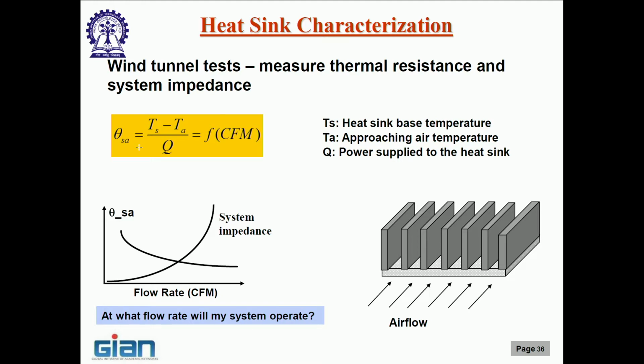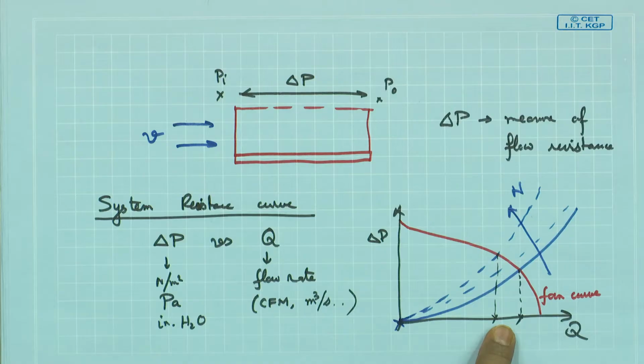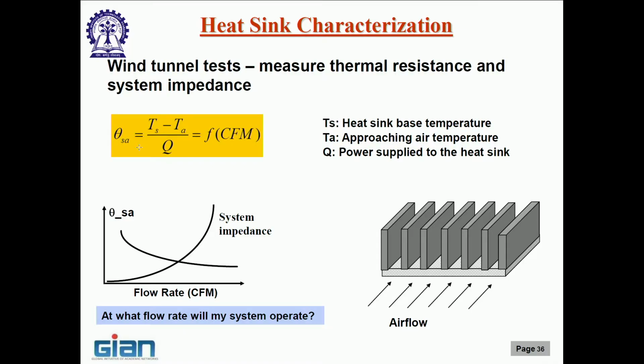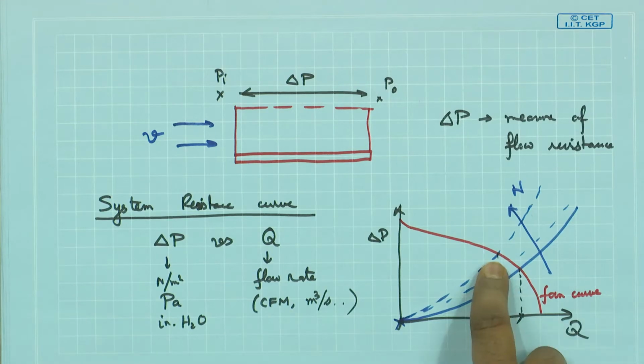So, having just a concluding note, having too many fins may help or hurt you. I mean, this by itself is not a disadvantage. So what? Okay, I am operating at a low flow rate, but even at this lower flow rate, the heat transfer coefficient and therefore the thermal resistance that I can give you is going to be lower than what I will give for this heat sink at a higher flow rate. Fine, I will go for this.